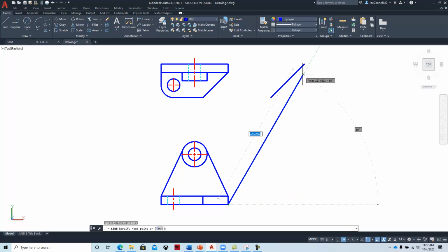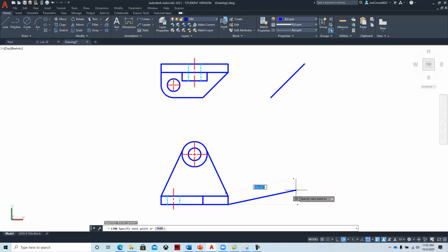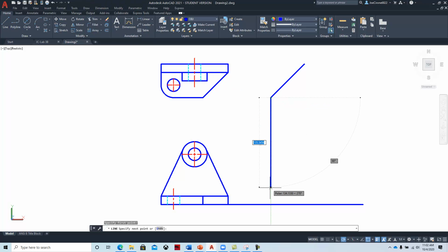And if you can't track these, and I'm having trouble tracking them, as you can see, just go ahead and put them and extend them. So this would go from here. Let's do it the way I would do it with a pencil. So the way it would work would be to get the dimensions from the depth dimensions in the top view to the side view. What you would do is project them from this point here to this point here to here.